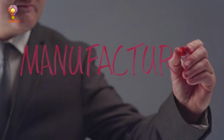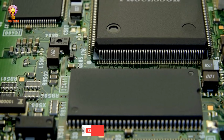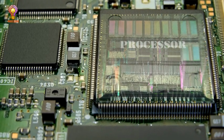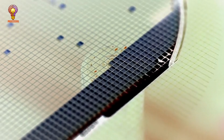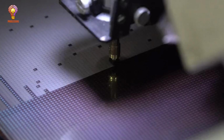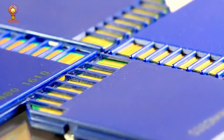2. Component manufacturing. Each phone consists of several key components manufactured in different factories before being assembled. A. Processor and semiconductor fabrication. The processor (CPU, GPU) is the brain of the phone, manufactured in semiconductor fabs, for example TSMC, Samsung, Intel. The process involves wafer fabrication, where silicon is turned into tiny transistors through photolithography, using UV light exposure on silicon wafers. Advanced chips are produced at 3 nanometer or 5 nanometer technology nodes, allowing better performance and energy efficiency.